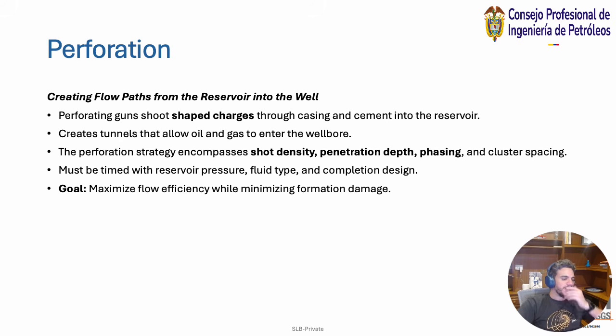And the reason you're doing that is you want to maximize your flow, and you want to minimize formation damage. And the reason we want to minimize that damage is because we want to control the pressure change and the integrity of the well and the integrity of the reservoir through that entire time period.